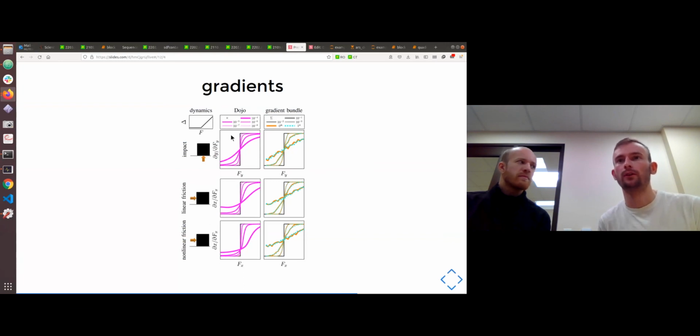For the subgradient method, I think this is the gradient that you get out of auto differentiation techniques. Also, this is what has been proposed with the DART simulator, for example. For the subgradient, it's computing the exact gradient of the stiff contact, of the stiff impact. As we've seen in these slides, the gradient of those stiff impacts is going to be like this step function. It's going to be very myopic in terms of providing information about the dynamics landscape. So it's not going to be very helpful.